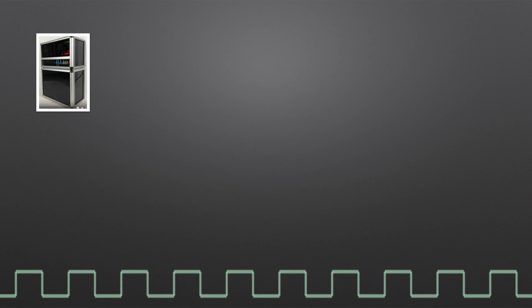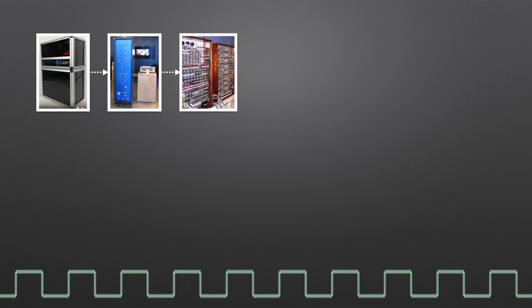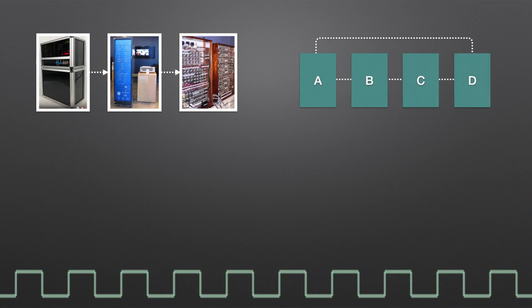I've mentioned a few times that my computer forms part of a lineage back through Phil Riley's and team's RC3, which you can visit at the San Antonio Museum of Science and Technology, by the way, right through to Dr. Harry Porter's computer. Both of these use a relay ring counter as a basis for their clocks. And that makes sense, a relay computer running on a clock which is itself made of relays. From a high-level viewpoint, you effectively set up a ring of relays which turn on and off in sequence. Goes something like this.